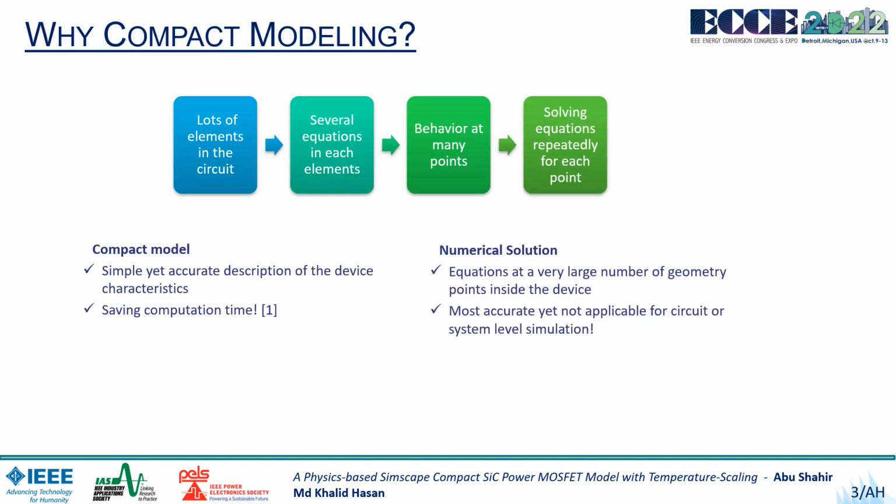So why do we need compact modeling? The circuits we use may have lots of elements. The model for each element contains many equations. The behavior of the whole circuit may be needed at many points. All implicit equations might need to be solved repeatedly for each point.